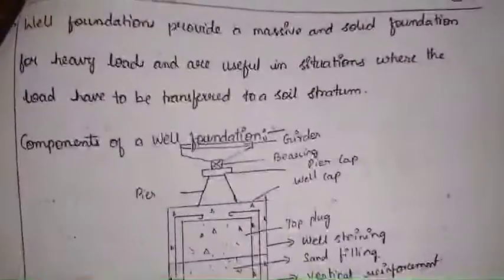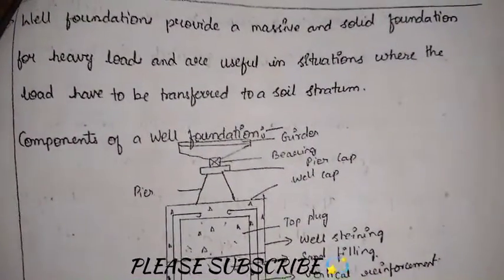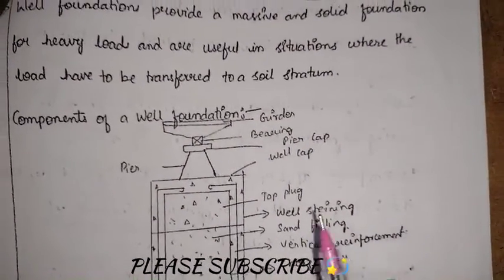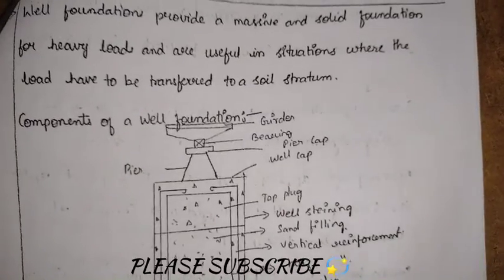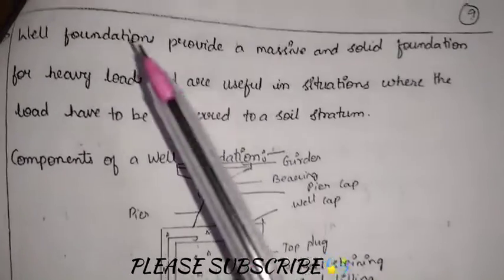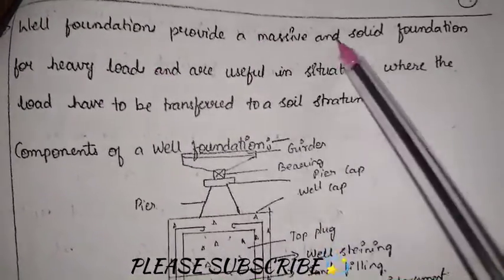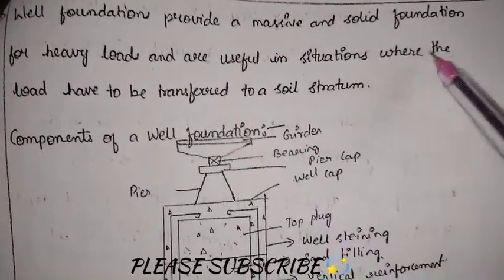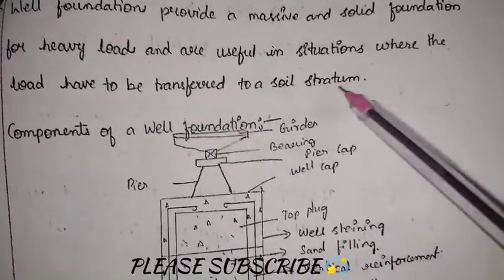In today's video, we are going to discuss what is a well foundation and the basic components of well foundation, what are the forces that act on this, and the basic shapes of this well foundation. Coming to today's topic, well foundations provide a massive and solid foundation for heavy loads and are useful in situations where this load has to be transferred to a soil stratum.